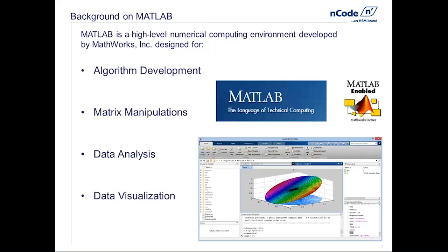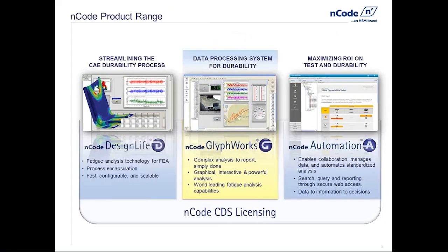Okay, so now I'm going to shift gears a little bit and step away from MATLAB for a second and spend a few minutes introducing you to some software that you may have never heard of before called GlyphWorks. GlyphWorks is one of three software products developed by a company called nCode, and it serves as a data processing system designed for analyzing measured test data. nCode as a company has two other software products, one called DesignLife, which serves as a fatigue analysis tool in the virtual CAE domain.